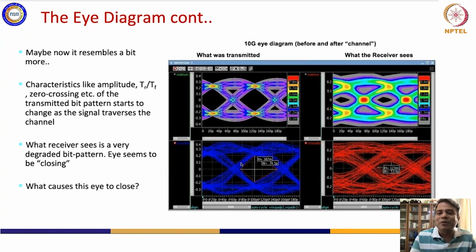And this is what electrical engineers who are working on circuits for high-speed networking would see. This diagram just represents that if there is a zero, it is mapped to the negative voltage, and if there is a one, it is mapped to the positive voltage, and the margin in between, where I have no bit present or no sample present, is my margin. That means my receiver can distinguish between a 0 and a 1. Why can it distinguish between a 0 and 1? Because the voltage levels are distinct over here. So if I have a comparator, I can make out what is a 0 and what is a 1 by comparing against a level crossing.